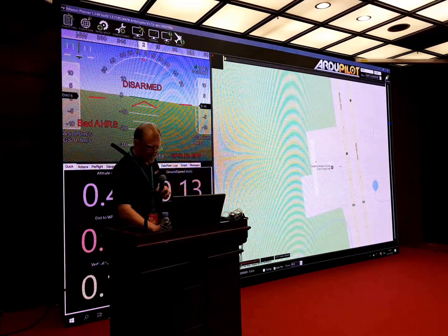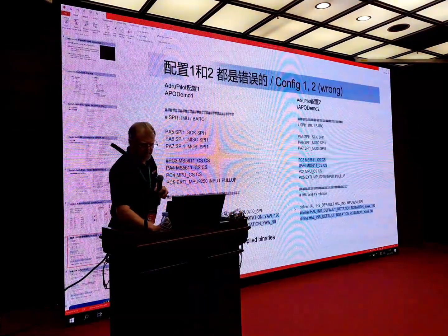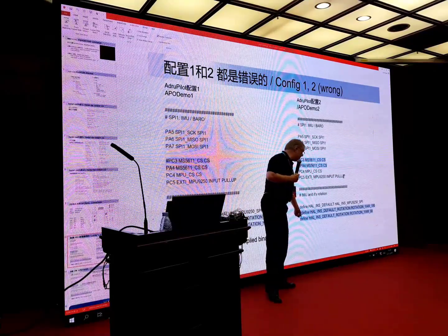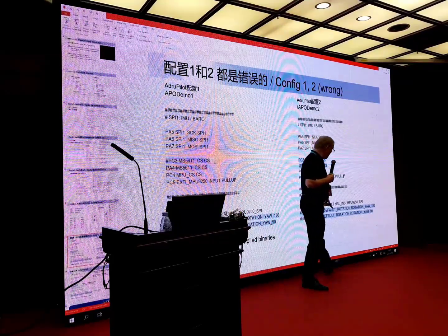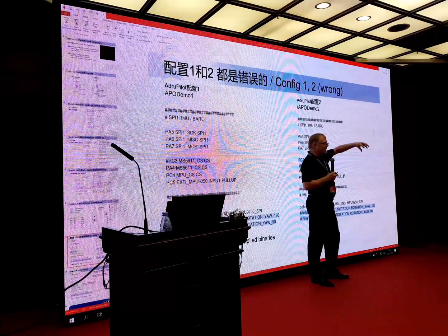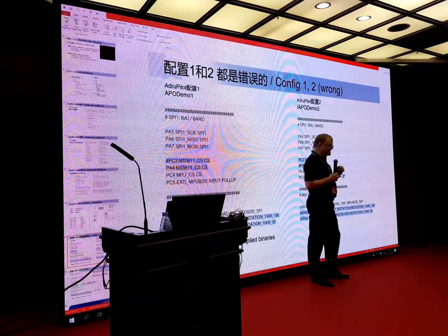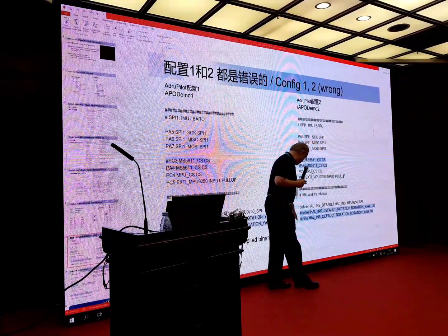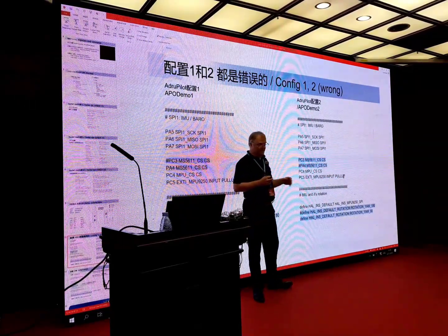Now, what did our configuration show? We are using this one. The yaw is only 90 degrees because the IMU is 90 degrees turned. Actually, it's not. It's 180 degrees turned. Then it would be okay. So this one configuration line is still wrong.